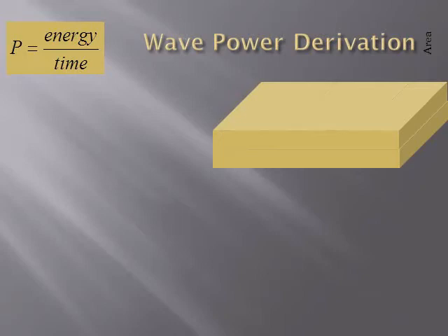We're going to lift some of this water up. So here we have a picture of a chunk of water, but this is when it's calm. In order to make waves, there are going to be low spots and high spots. So we're going to pick up some of this water and stick it on the high spot, except we are going to assume, just because it makes our life very simple, that the wave is square. I know, a square wave. That's ridiculous, but whatever. This is apparently what the equation they give you is dependent on. This is why it took me so long to figure it out, because it didn't occur to me that they would use a square wave.